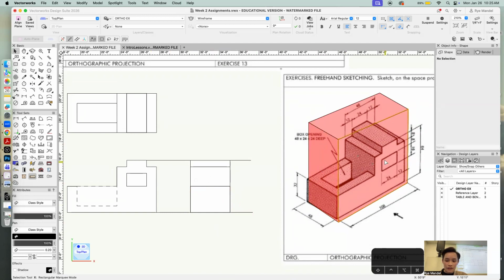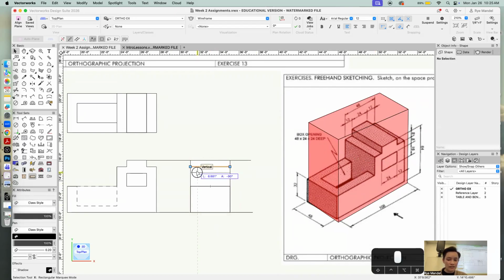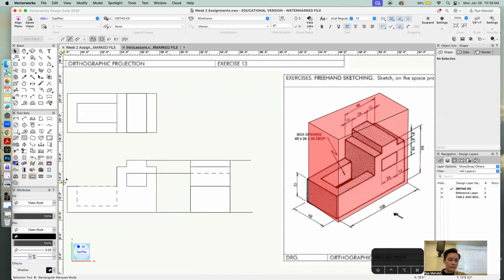Another thing that is here is this smaller little rectangle. That's a hidden one because it's inside, right? So we're gonna create another line for that one. And then we're gonna bring the line down because that's another thing that's inside of it that's hidden. So I hit 8 inches and then I'm hitting shift and then releasing. Another way you can do it is to just take this and snap it over so you know that's right there and you know that's hidden. And then you can make this a hidden line, and just snap this over just to make sure that it is this one.